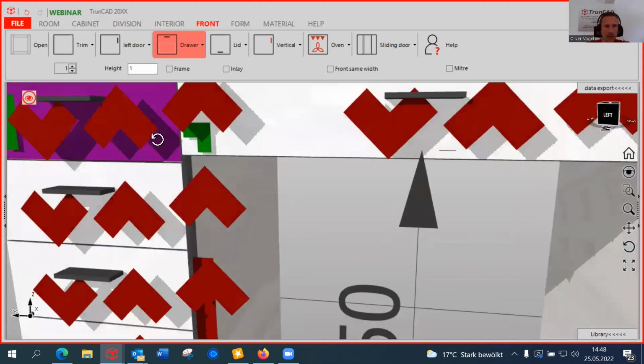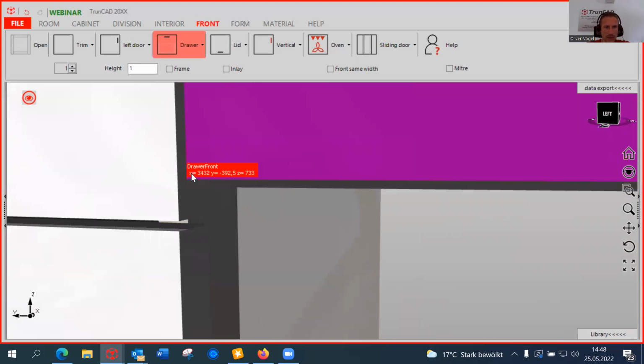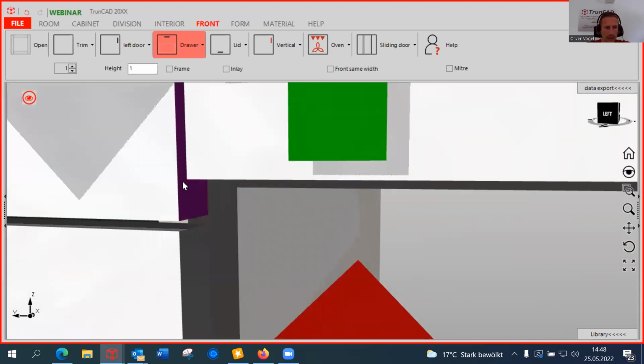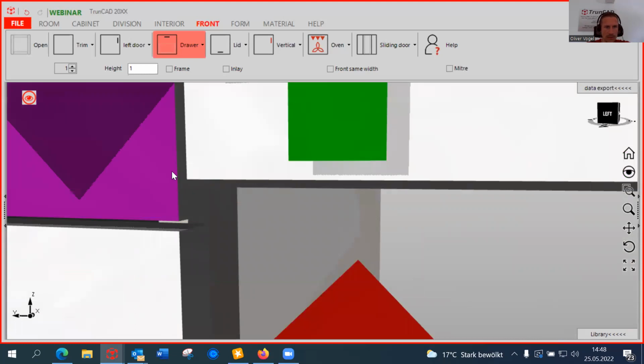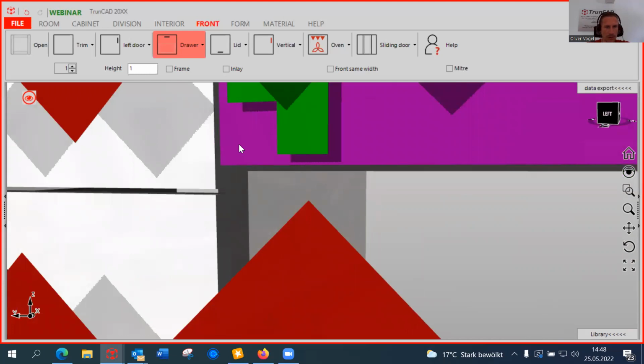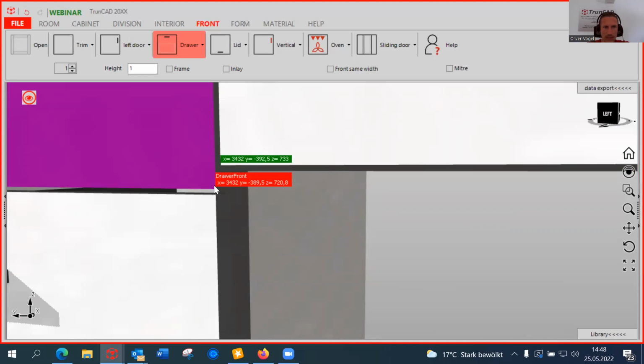So, when we want to have it here on the same level, we also need to measure the difference in here. Yeah, so we keep the control button pressed. Then you see also when we keep the control button pressed, the smart clicks are disappearing immediately. Yeah, and then we click here to the corner point, where we see the coordinate. We click it with a left mouse click, and it's turned to green. And we do the same here for this. And then it's measuring the distance.